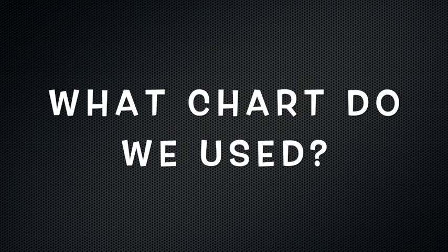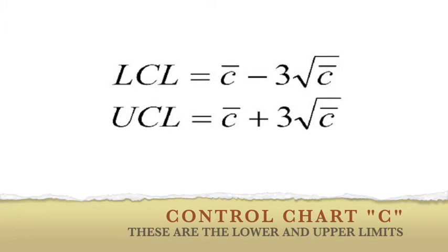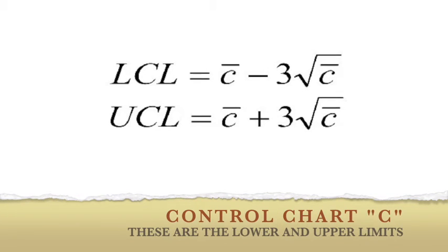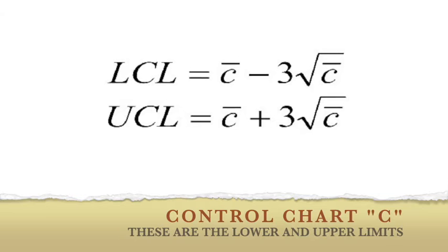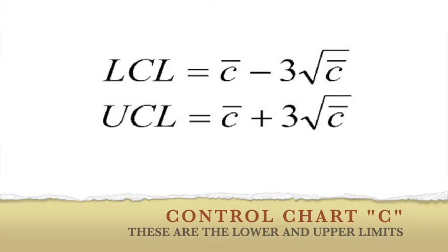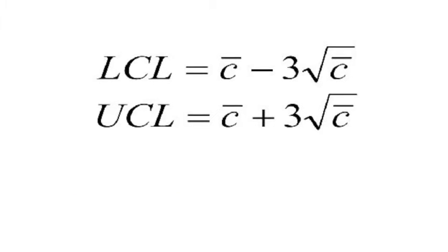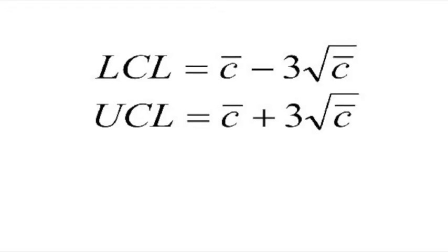The control charts were created by Shewhart during the development of statistical quality control. Graphics are widely applied in the control of industrial processes. However, there are different types of control charts for means, ranges, proportions, and attributes. But for this project, the control chart that we will execute for the number of nonconformities without a given standard value is the C control chart. The C control chart is a tool that allows us to analyze the variability of the number of defects per group.